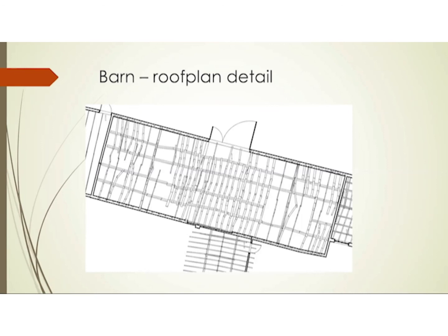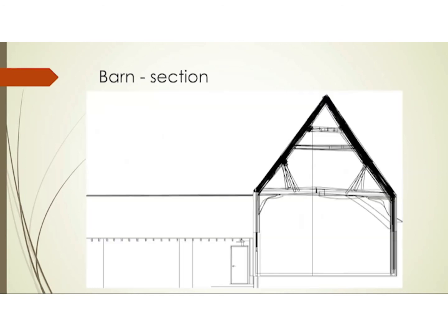Your survey detail must be captured at a small scale, I think that's the word. So 1:20 or 1:50, 1:100, and be careful that that's appropriate to the scale at which you intend to design from the data that has been captured. That's quite a technical point, but I'm sure it'll make sense to one or two people at least.